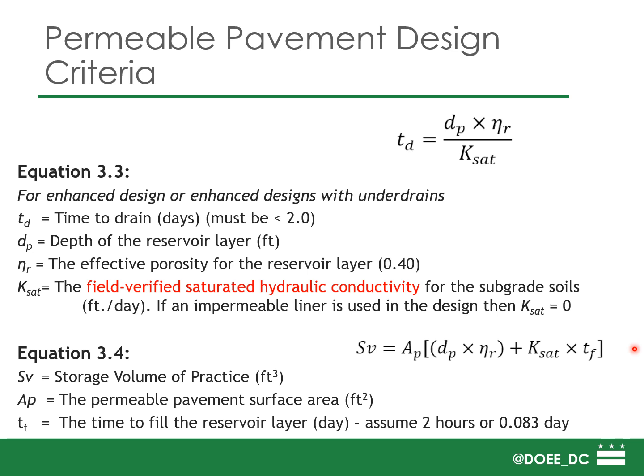The storage volume of the practice is calculated by equation 3.4. It is the area of the practice multiplied by the storage depth in the permeable pavement layer, the depth of the practice times the porosity, plus an additional bit of storage that accounts for the dynamic nature that, as the reservoir layer is filling up, some infiltration is happening.